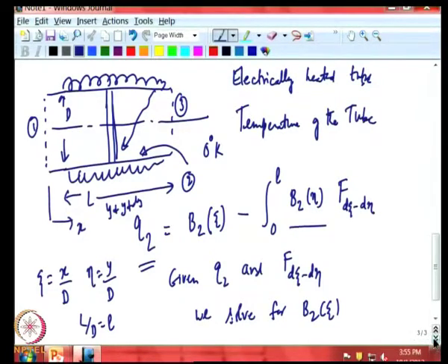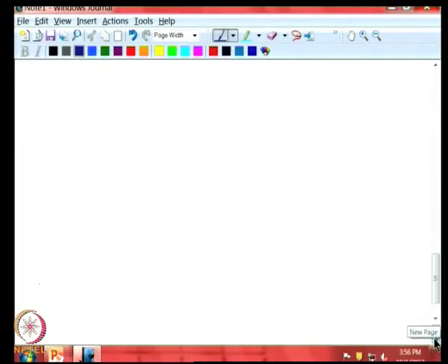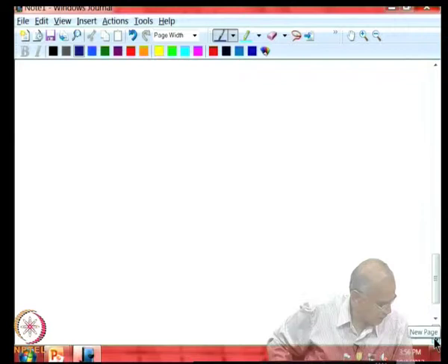Now, before we go to that, we need to look at what is called the kernel. So, in an integral equation, you have the unknown function here multiplied by a kernel, and the function also appears outside, and that is a non-homogeneous term, which is the specified heating. So, what is this kernel? This kernel you can easily obtain from standard tables for shape factor.